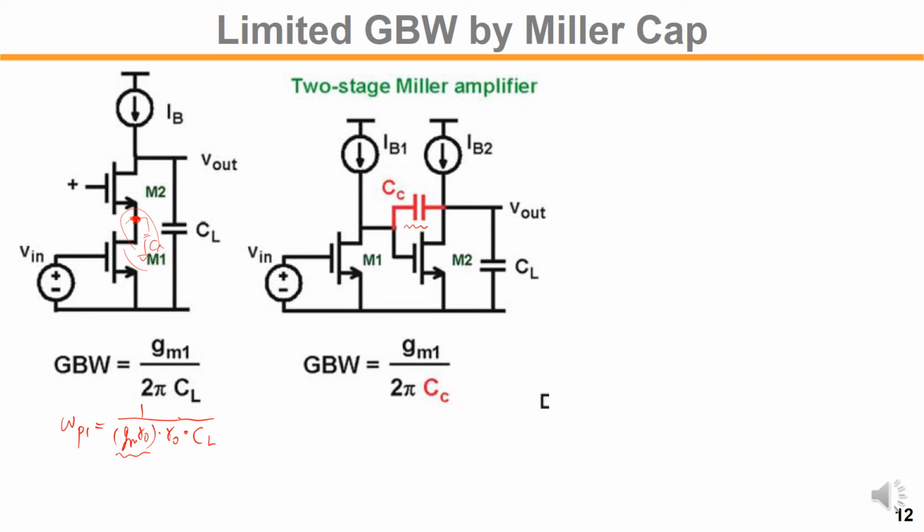So we'll consider just the dominant pole for now for this cascode. For the cascade case, however, we have a dominant pole omega P1 at that M1 output, so 1 over resistance ro times CC, boosted by the Miller effect, so CC is boosted by the second stage gain, that would be gm ro, right? So surprisingly, the dominant pole location would be similar in cascode and cascade.